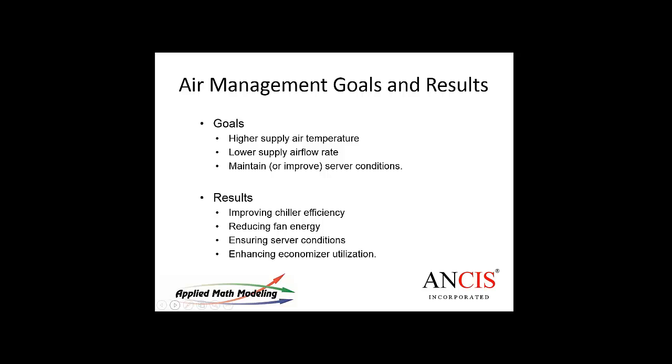So I guess the goals here are for higher supply air temperature and lower airflow rate to optimize the servers. In the case of the higher air supply temperature, that's an energy issue as well, right, Magnus? I mean, if we get higher supply air temperature, we're going to improve the efficiency of the cooling system. And if we reduce the flow rate, we get two benefits from that. We, number one, reduce the bypass airflow, and number two, we also reduce the requirement for fan speeds. I guess the third one is, by definition, it increases the return air temperature because if the air rate is slower, then it has more time for heat transfer and therefore higher return temp, right?